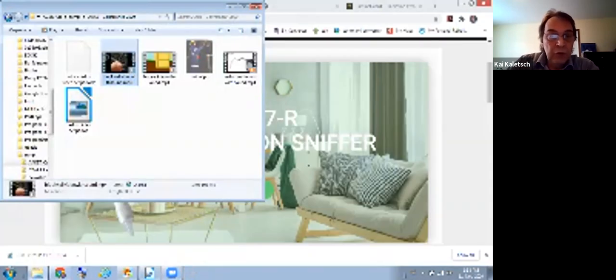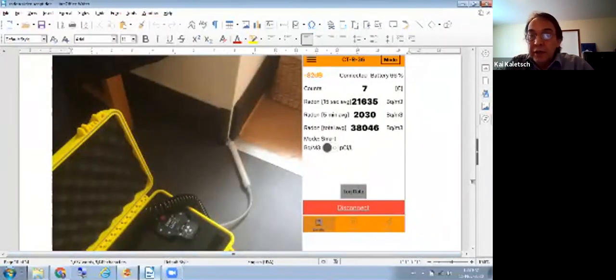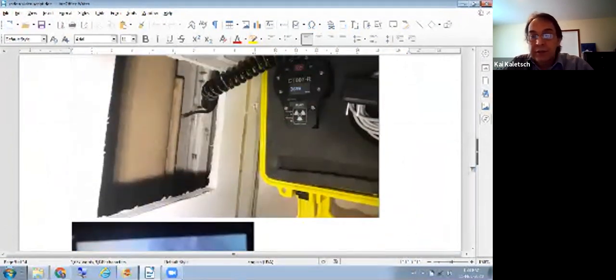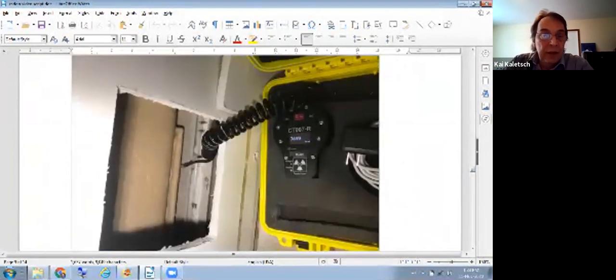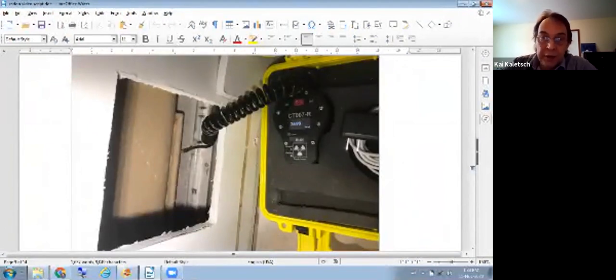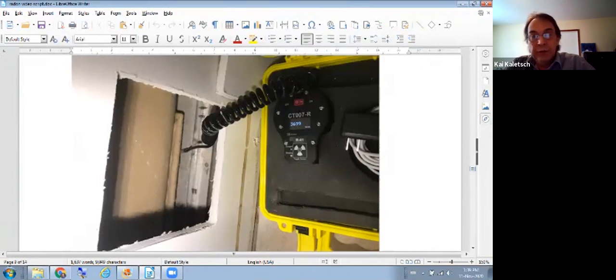Sometimes you don't necessarily want to drill holes all over the place if the place is already finished, so you don't want to necessarily do all your diagnostics like that. So some people are using the sniffer without actually drilling holes through a slab. In this case here, that is a commercial job at a university. This is in Canada, so the units that are shown here, the 3700, that's in becquerel per cubic meter. So that's 100 picocuries per liter. So he's sniffing below a bathtub in, I think, a university dormitory. And he's finding 100 picocuries per liter.